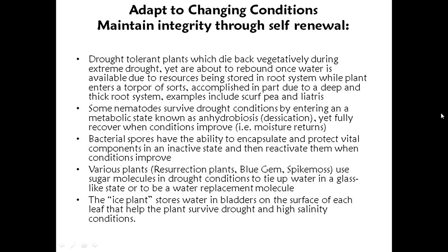So you see some things where the water storage is both decentralized and redundant, so there's a lot of backup. As humans, we've gone with the large reservoir model, and of course the opportunities to do this are becoming more and more difficult to find. There's a lot of damage with these. So people in LA have proposed to put in cisterns to capture water from parking lots, from roofs, etc., and then use that for irrigation in a decentralized fashion. This not only catches stormwater that wouldn't be used, and then it's able to use it later when you need it, but also it reduces the peak stormwater flows, which is a big issue in a place like Los Angeles that's so heavily developed.